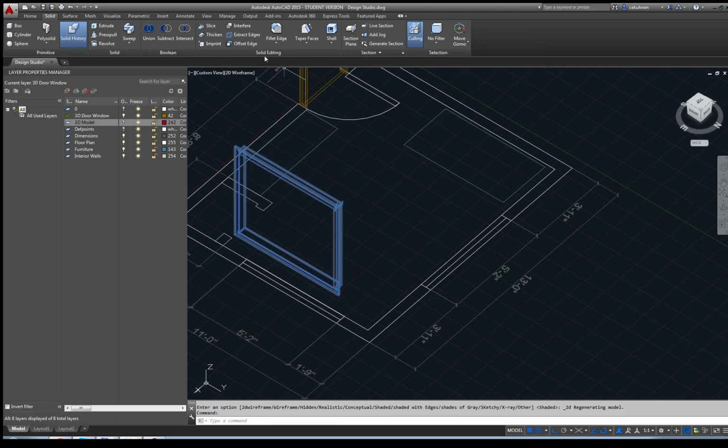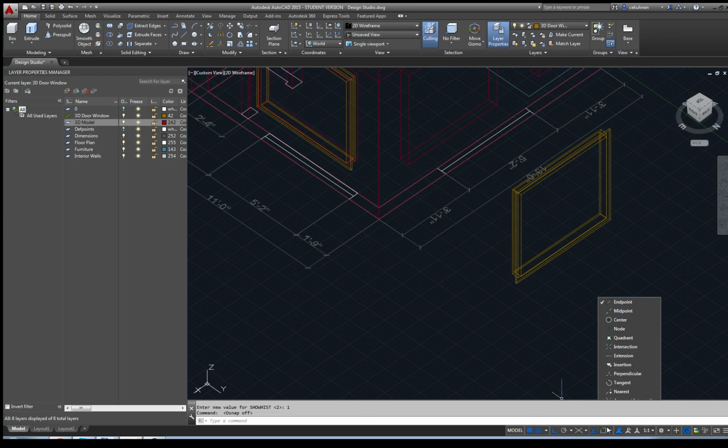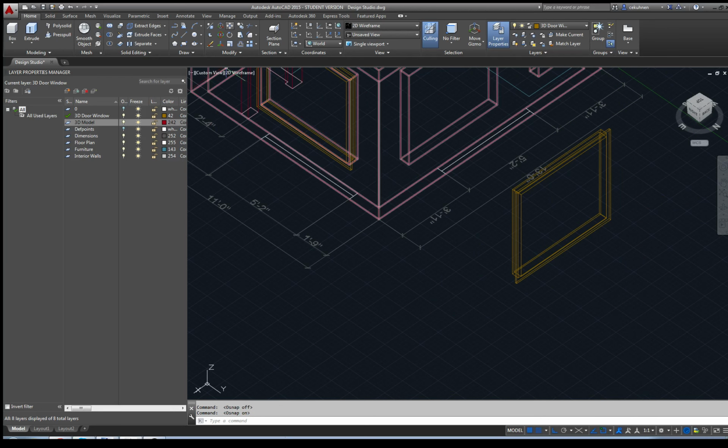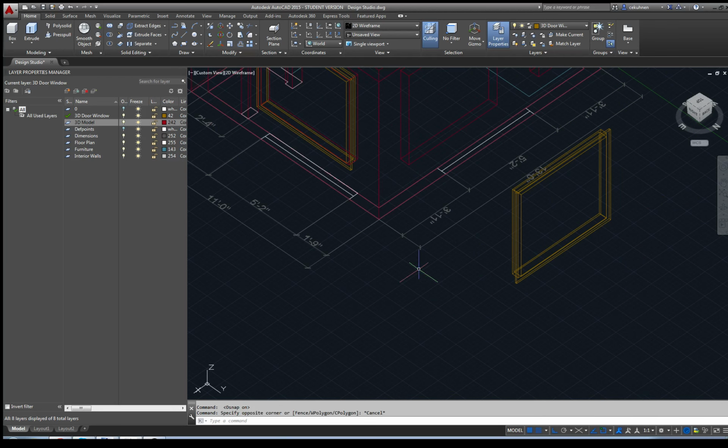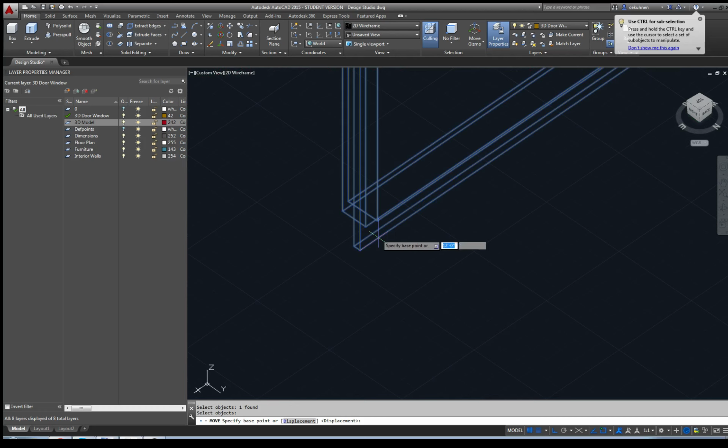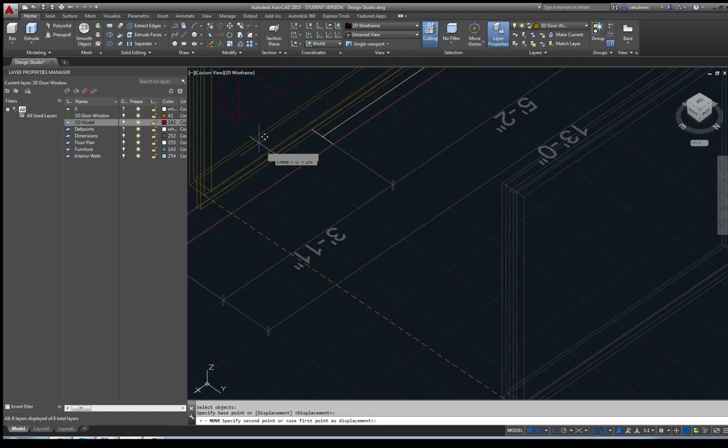So for right now, I turn show history to 1. So I would like this point where my mouse is right now to snap to this corner there. So let's check, turn this one off, go to, for example, type in move this object from this corner to this corner, click.